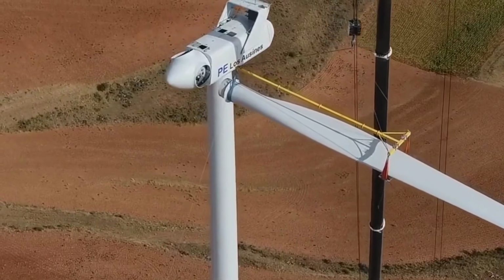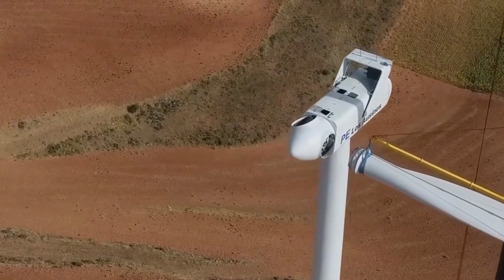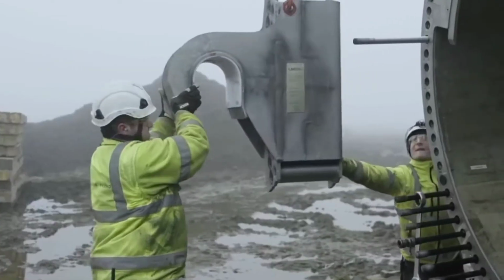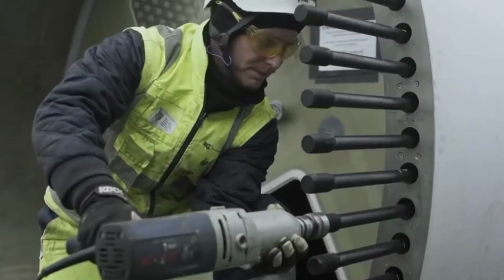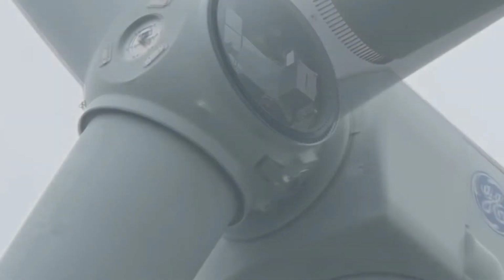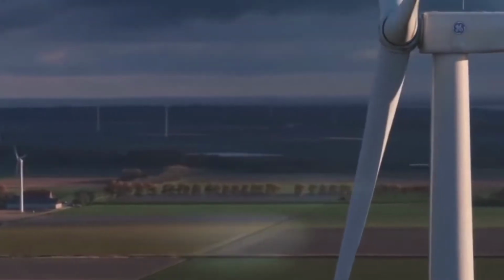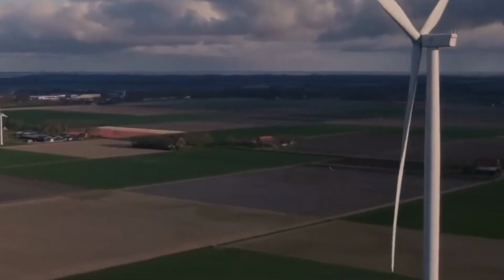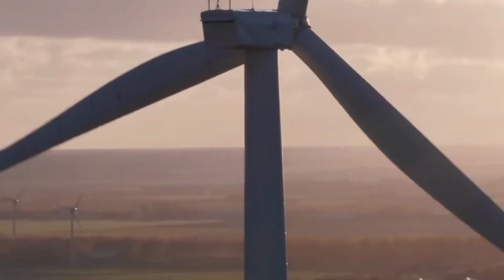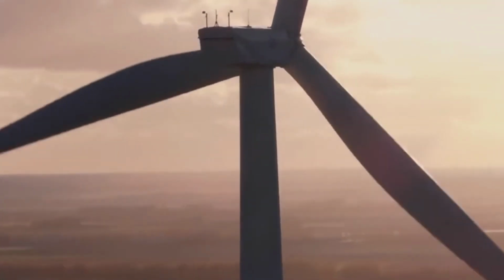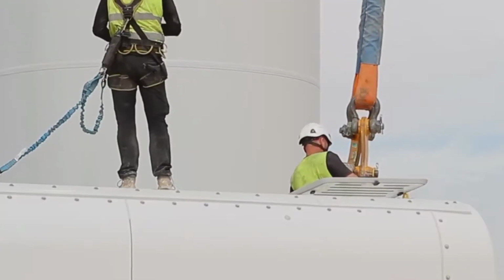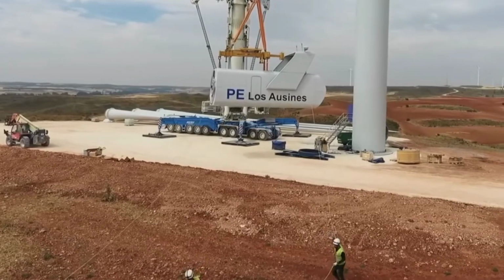The nacelle frame is made of 2 main parts. The front or main frame of the nacelle is made of cast steel and holds the yaw system, gearbox, and main shaft. Another part includes the generator, transformer, and electrical cabinets, which are secured to a rear frame made up of welded steel. Once the yaw system passes its rotational test and its motors are installed and pass their functional tests, the 2 halves of the frame are joined by heavy bolts and spring pins.